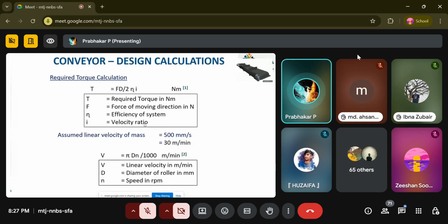So the pulley ratio is 1:10, which means it reduces the speed by 10 times. The 10 Newton meter motor times 10, you'll get 100 Newton meter as output. At the same time, if the motor runs at 1000 RPM at the input, the output will be 100 RPM, because the torque is increased 10 times and the speed is reduced because of this gear ratio.